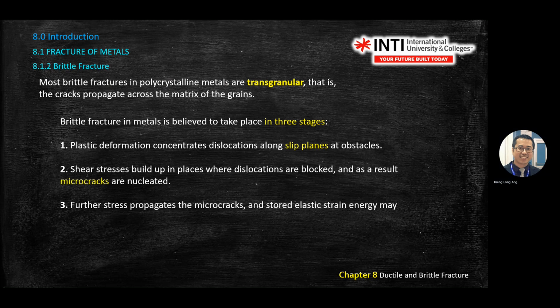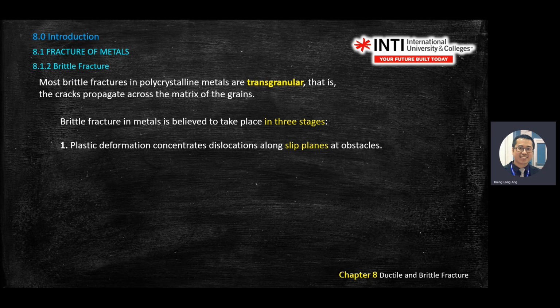Okay. Brittle fracture also has 3 stages. Just now you saw ductile, right? Ductile starts with a small cavity. Don't use the word bubble, use cavity. Cavity turns into crack. Crack turns into cup and cone. That one is for ductile. So there are a few keywords there. So cavity. Let me show you the slides.